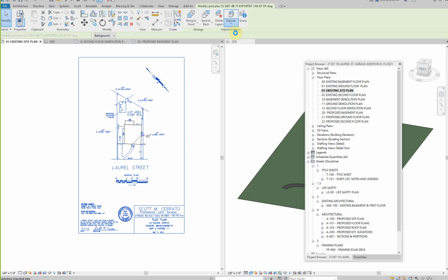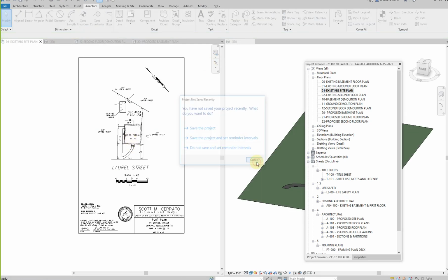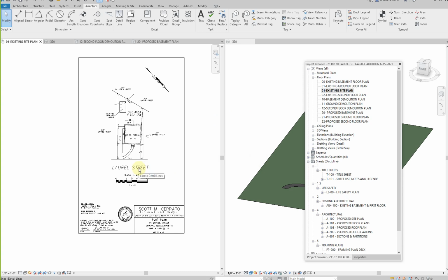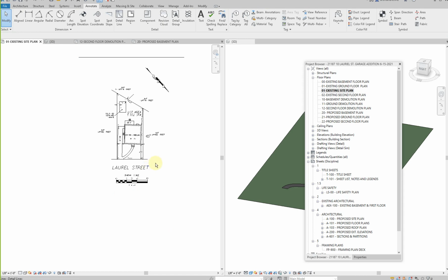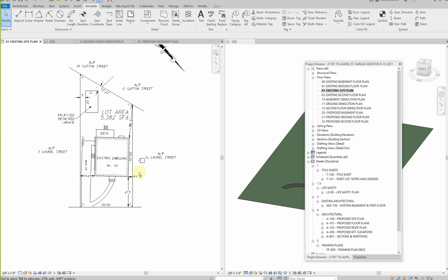So what it does is really that it embeds the vector file into your Revit model. So check what happened. Check it out. So now it really made all of these elements into embedded elements within your Revit file. Now there are good things about it and bad things about it. Why are the bad things about it?